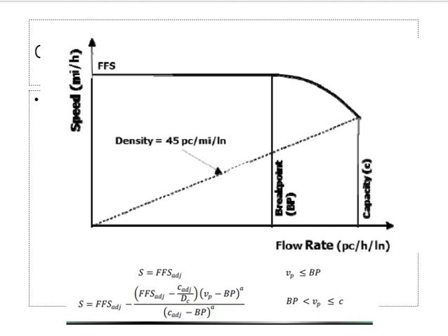This is how we fixed it, according to the range of level of service. The last value of level of service E is 45. So this becomes my critical density, density at capacity.